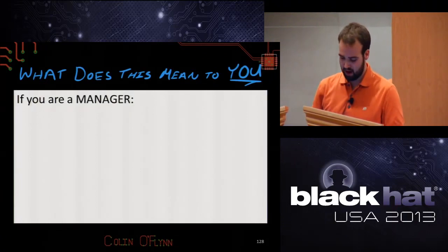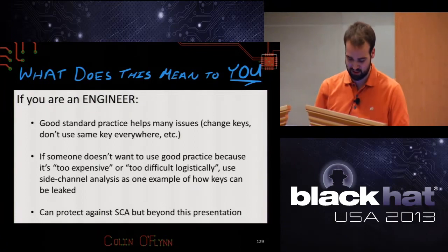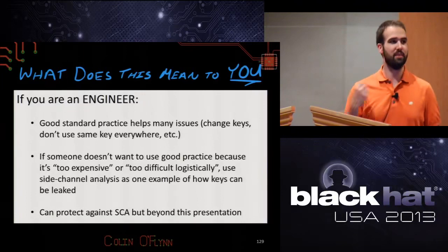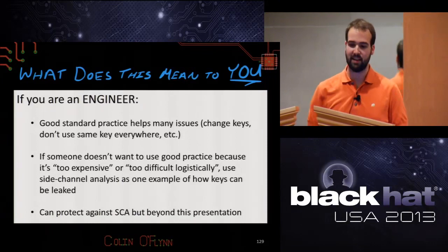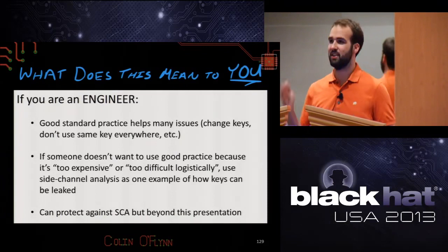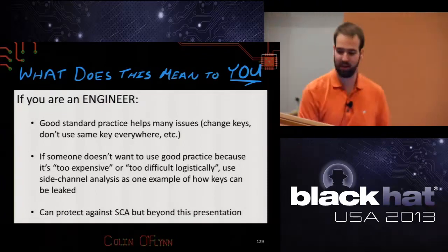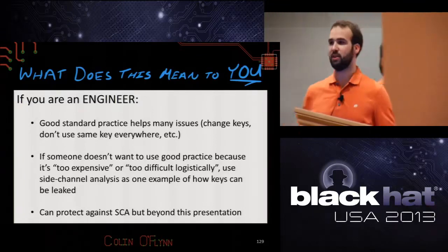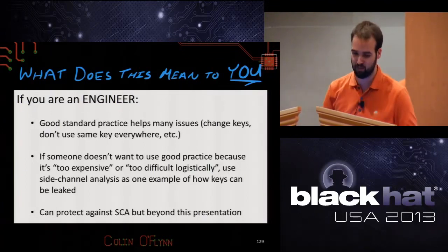So for the high level, if you're a manager, I don't really know because it's all technical to me. If you're an engineer, good standard practice does help this issue already. If you use the same key in all your devices for the bootloader, you probably know that's bad. The problem is that a lot of people don't want to use good practice because they say, well, that's a hassle. I'm not going to have different devices with different keys in their bootloader and then different firmware files. So maybe this is a good way to point out a reason we should do it, because here's an easy way people could be breaking our systems. And so you can use this to point out why we should use good standard practice.